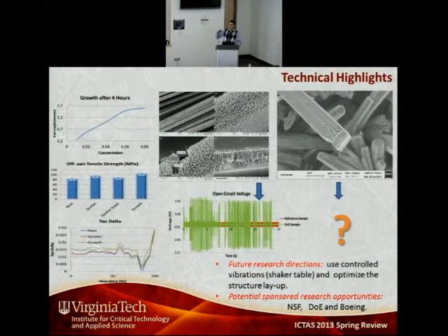Then we have sputtered a layer of zinc oxide. Then we have used the same sputtered layer, but we have put it in the same experimental conditions as the growth sample, meaning in water for 4 hours at 80 degrees Celsius. And then we have prepared a sample with the growth. So the growth sample is FRP composite with zinc oxide on the surface of the carbon fibers.